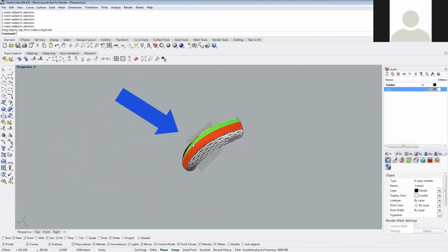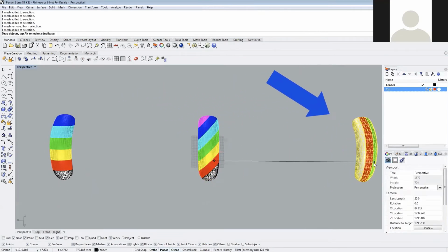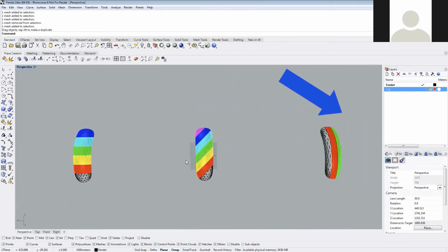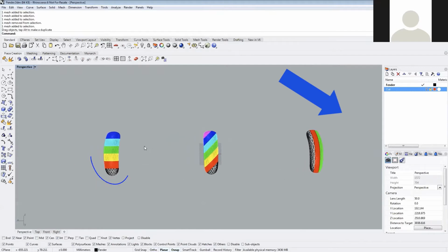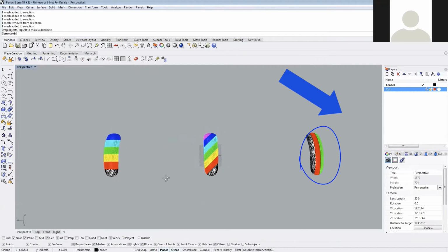We're going to rotate under. We're going to select our C layer. And again, we're going to just drag this off over here. We're creating physical separations. Now we can very easily, clearly see we've got our A pieces over here, our B pieces over here, and our C pieces over here. So at this point, we can continue on with the standard composite flat workflow.